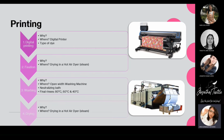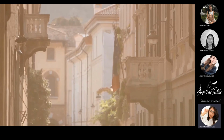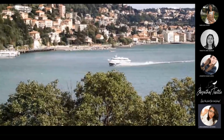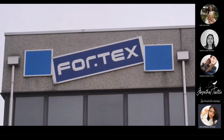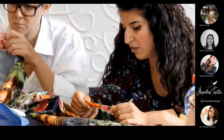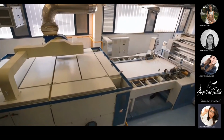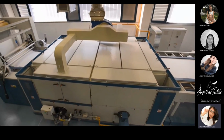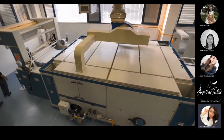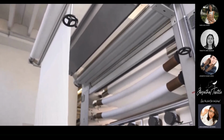The printing pattern is given to add colorful designs to the textile, and it is done in a digital printer with reactive dyes-based ink. The temperature of the room which has the digital printer is 15 degrees Celsius to avoid the clogging of the printer head. The printed pattern is dried at 80 degrees Celsius in the hot air box, and the fixation is done at 120 degrees Celsius.